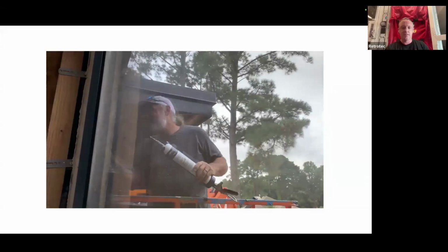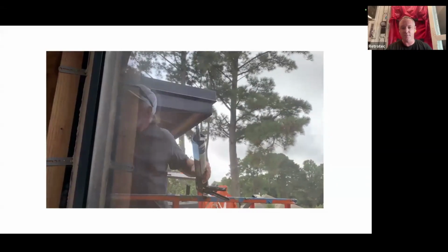That's one of the reasons why they missed it, because it was way up under a soffit. But it's a good thing that we did that before they put up those soffit boards underneath, or else they'd have to pull them back down to really get to it. So that's some blower door assisted air sealing: use fog and the blower door at the same time, have somebody else outside to spot it, see where it's coming out, and then do something about it.